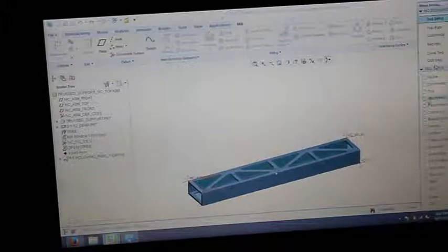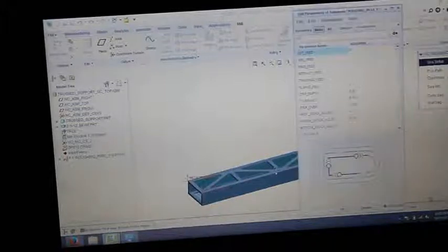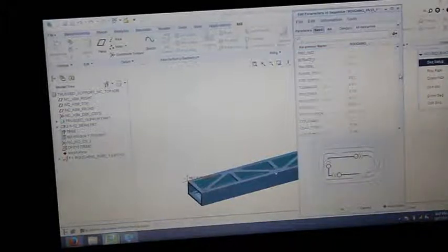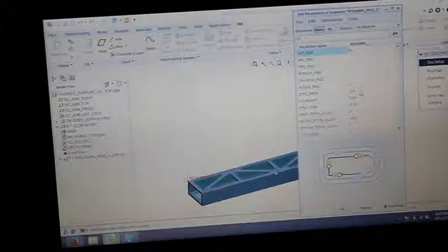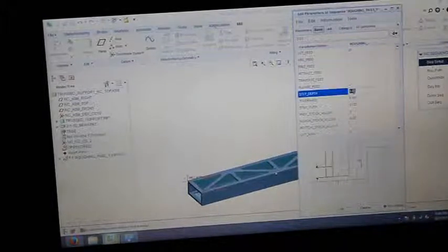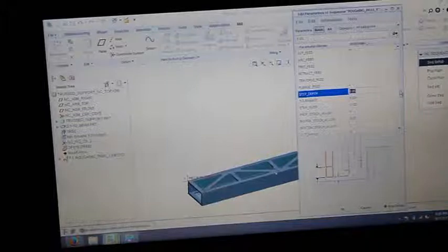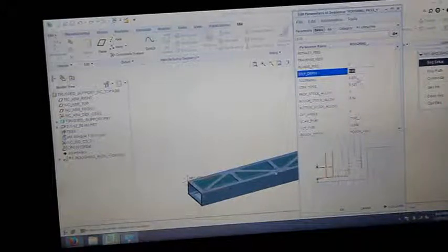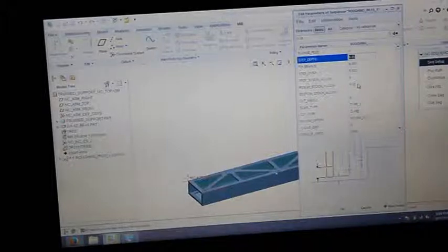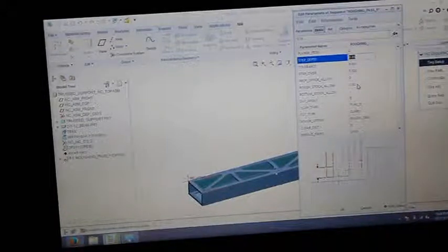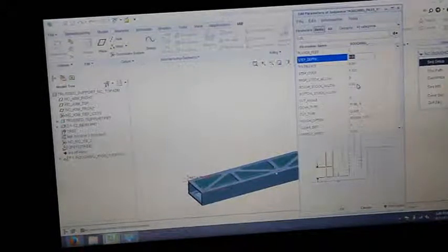And then we go back to sequence setup, go back to our parameters, hit Done, and now we can look at some basic information about what the cut's going to be doing. So our cut is going to do a feed rate of 20 inches per minute. This is our depth. This is how far it cuts down each time. That's roughly 0.05 inches. It has its tolerance, how much is stepping over each time it's doing a cut, and how much we're leaving for the next number of passes to operate with. So in this case, we're leaving 0.02 inches to work with.